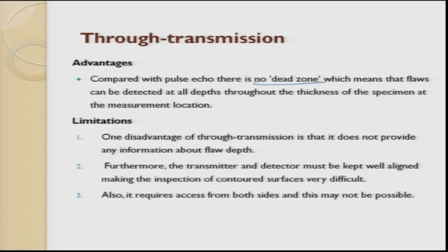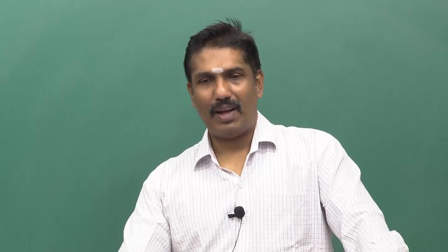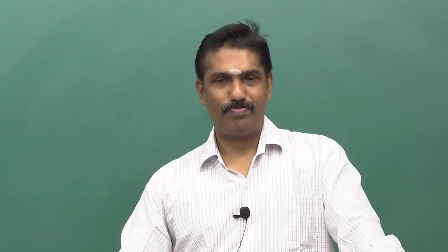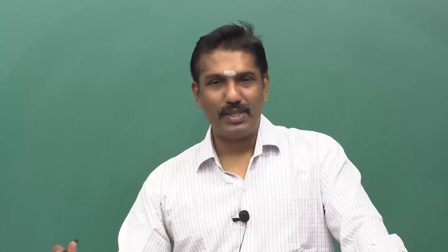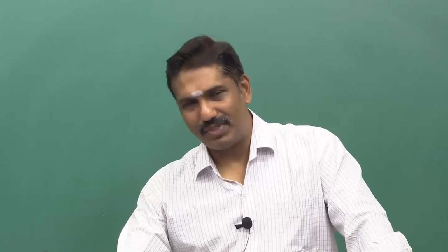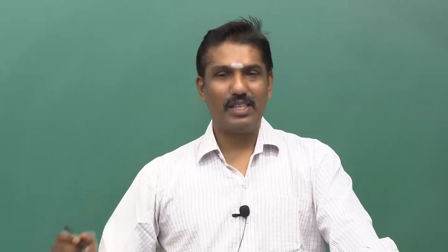Interestingly, when I was discussing all the processes, I was trying to talk about one parameter called surface roughness. I was saying that the surface roughness on both sides is very good, or the surface finish is smooth. When I use these composite materials, if I have a rough surface and I use ultrasonic techniques, then there is a problem with my signal interpretation.